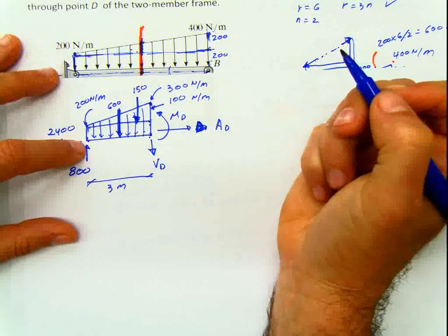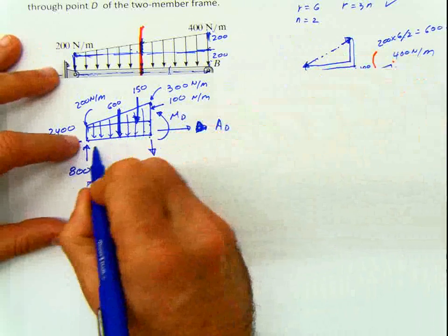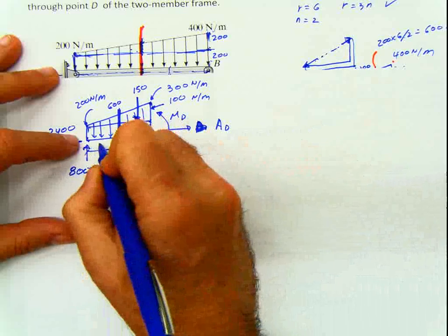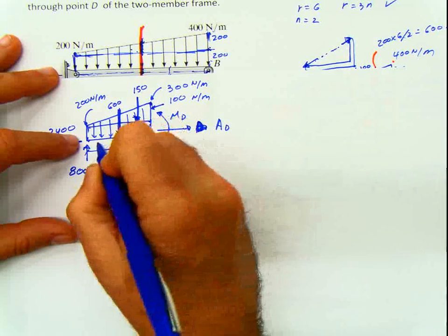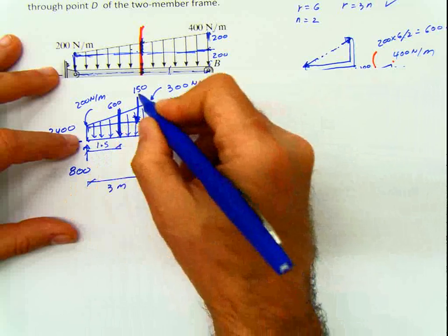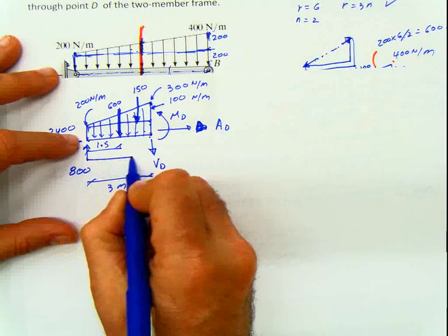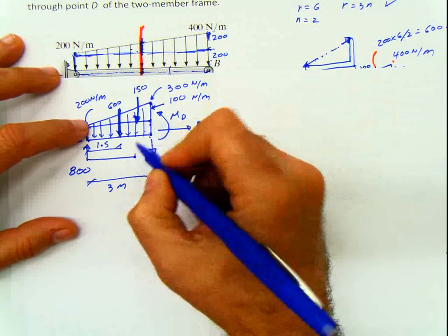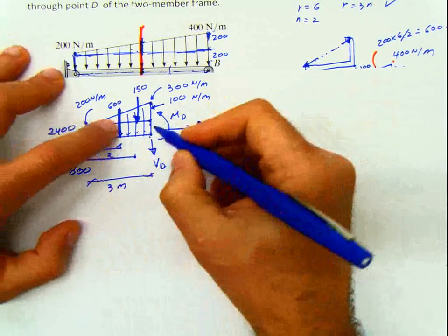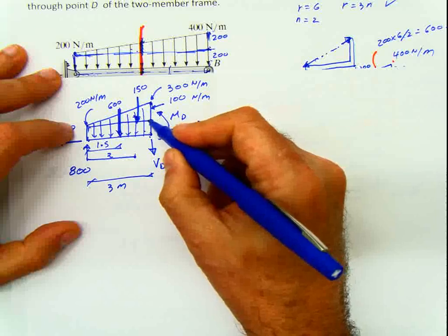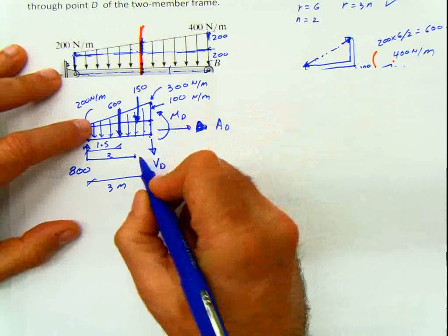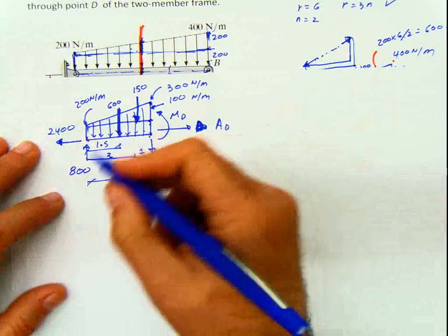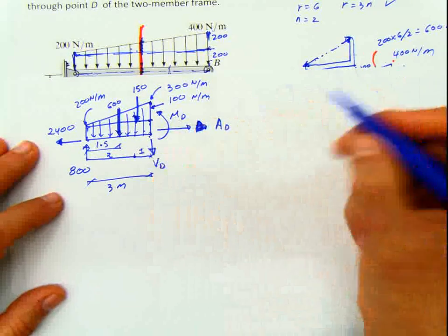The location of the forces again, the rectangular at the centroid, which is half of the rectangle, and that is 1.5, and the 150 from this end is going to be 2/3 of the base. 2/3 of 3 is 2, or from this end, from the right angle, is 1/3 of the base, and the base is 3, so the distance from here to here is 1. Once you have all the distances, just proceed.